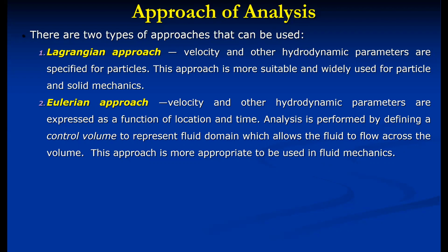The Eulerian approach is also called a field approach. Generally engineers use this particular approach. In our fluid mechanics also, we are going to use the same approach, where a particular flow domain is monitored, and the behavior of particles passing through that particular flow domain is monitored with respect to time as well as with respect to location.